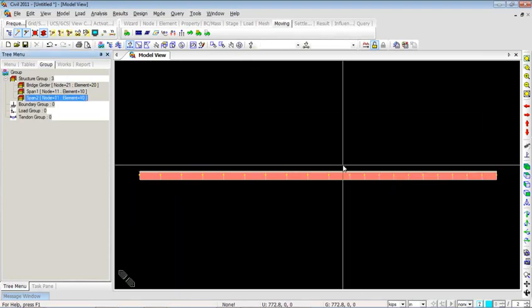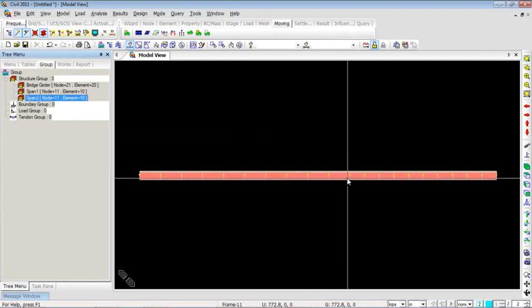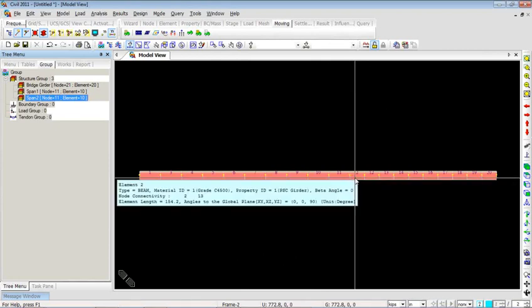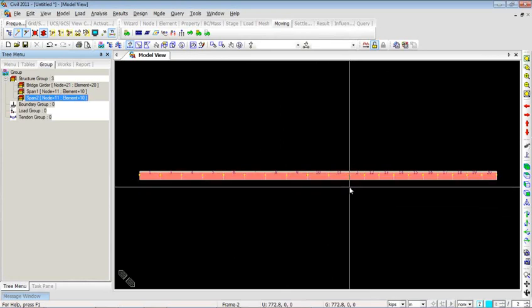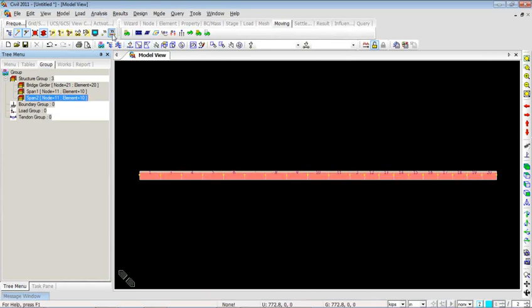Now how I figured out where span 1 ends and span 2 starts is the difference in the segment division. As you can see, the spans whose numbers are 11 and 2. 11 is 1/10 of 184 feet, whereas 2 is 1/10 of 128.5 feet. So the difference in the length goes to show where the two different spans start. Now let me display the node numbers or the element numbers. And having defined the structure groups, now I can proceed to define the lanes.